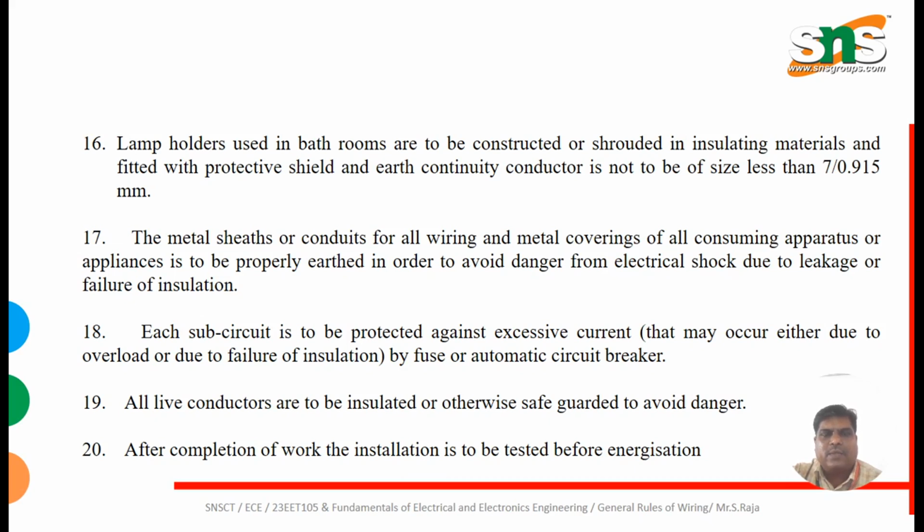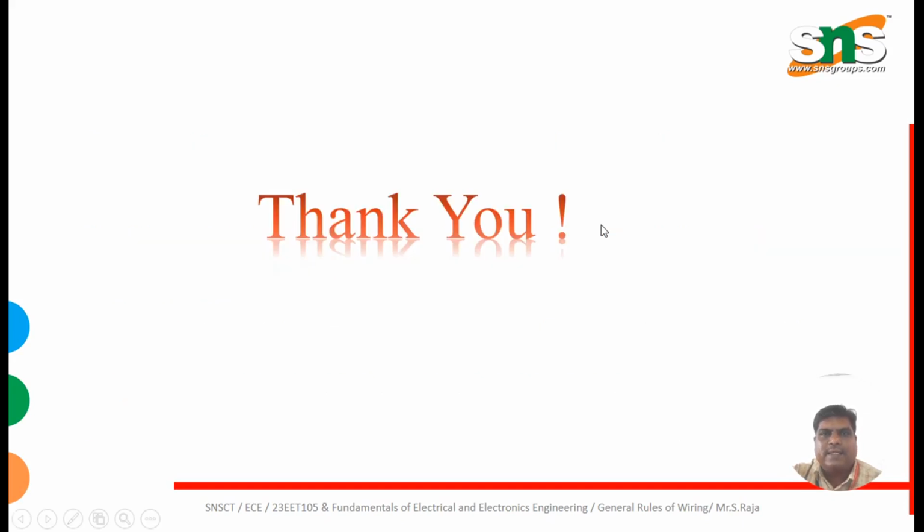Each subcircuit is to be protected against excessive current by a fuse or automatic circuit breaker. All live conductors are to be insulated or otherwise safeguarded to avoid danger. After completion of work, the installation is to be tested before energization.